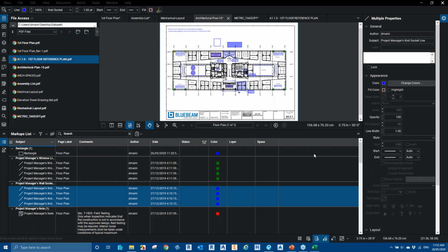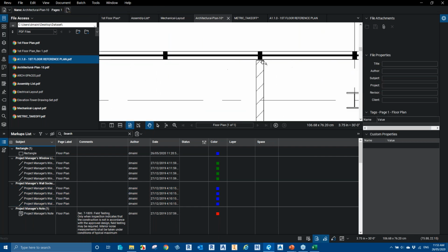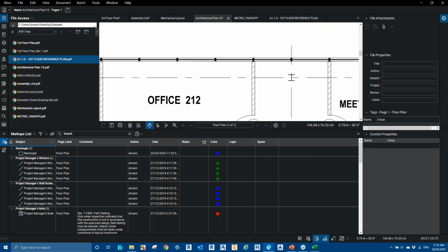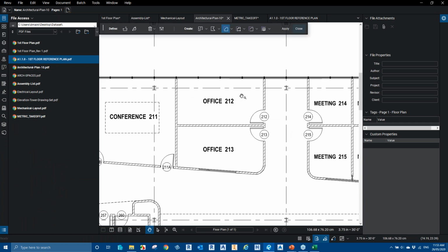I'm having trouble with the dynamic fill stopping at the edge boundary. Yes, so Misha, that could be. For example, let's say if I just hide this. If there are openings, for example, see how this wall has a little opening here. And if I'm creating a dynamic fill, this would leak out of this region here.